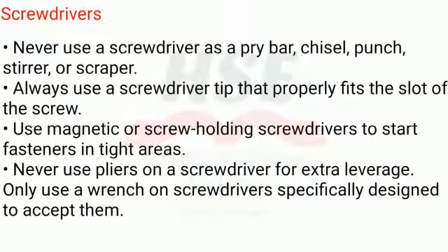Screwdrivers. Never use a screwdriver as a pry bar, chisel, punch, stirrer, or scraper. Always use a screwdriver tip that properly fits the slot of the screw. Use magnetic or screw-holding screwdrivers to start fasteners in tight areas. Never use pliers on a screwdriver for extra leverage. Only use a wrench on screwdrivers specifically designed to accept them.